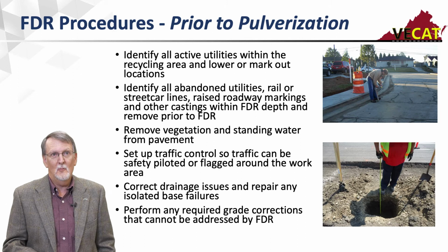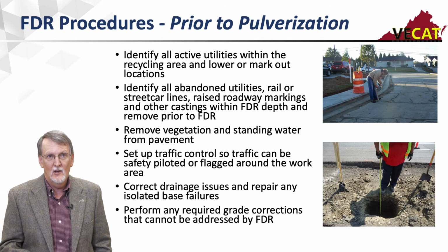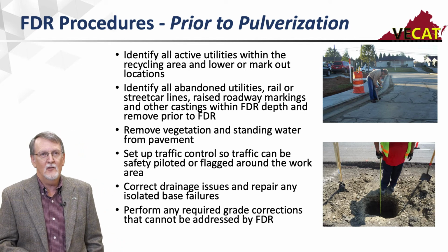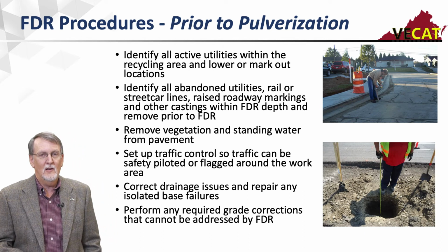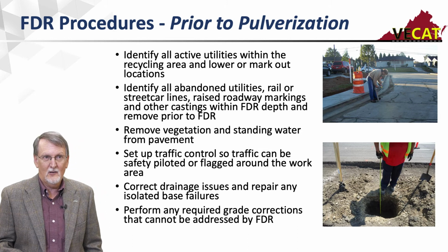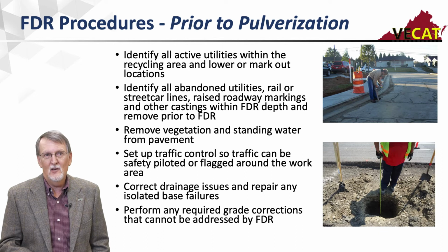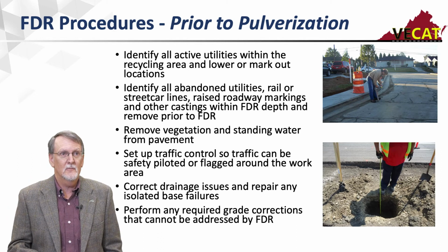So, especially in an urban area, any old rail or streetcar lines, any raised roadway markings, or other castings. And I want to remove those prior to FDR. The one thing you do not want to do is to hit a manhole cover with that reclaimer, because that could be real exciting. Or if I hit any of these other utilities or chunks of iron, at best, I'll break the teeth off the drum. Worse, it could be very serious.